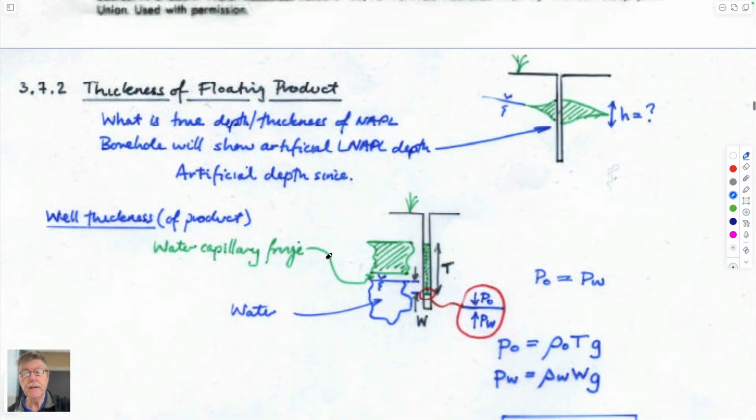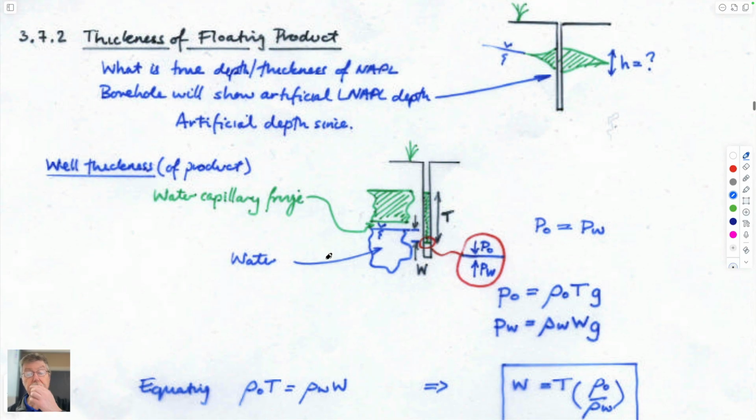So to do that, then we could think about drilling a hole. So to be able to get the picture for your assignments, that you're sitting in a field and you know what's going on, that has to be got somehow. Typically you drill a hole. And the question is, how do you measure exactly how deep this puddle might be in the subsurface, because you can't see it. So the only way you can do it is to know where it rises to in that borehole and where the water gasoline interface is below that. And that would give you a thickness of product which you could use to make that calculation.